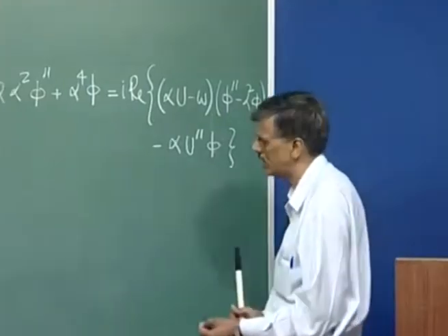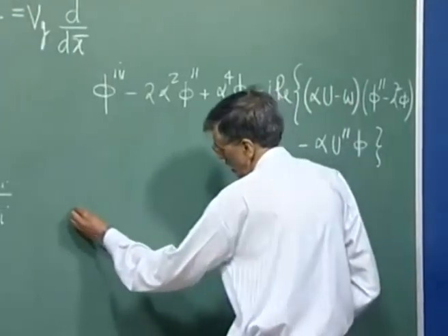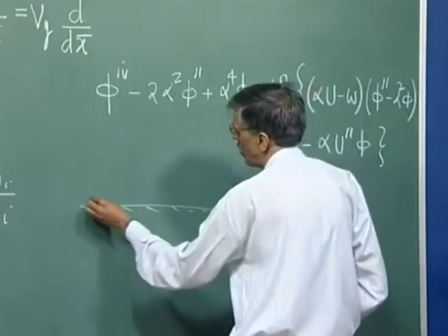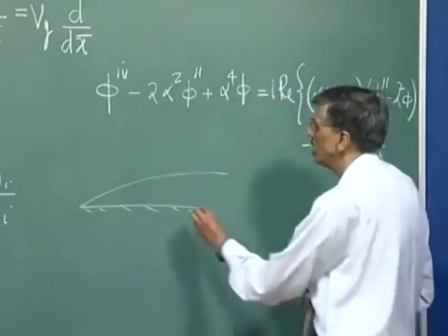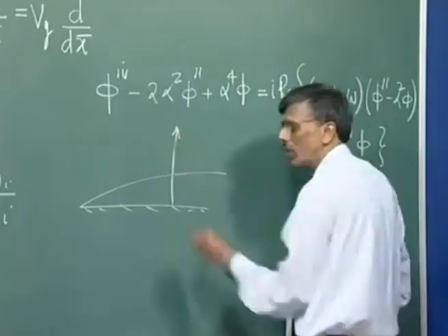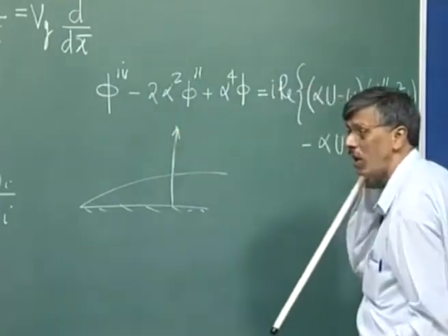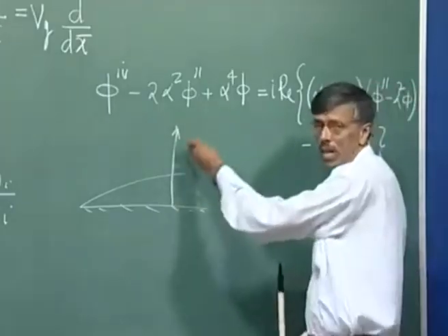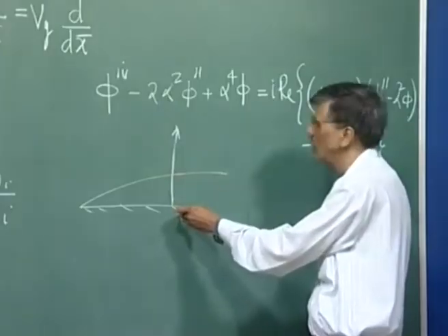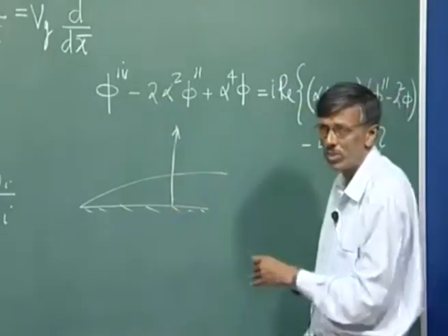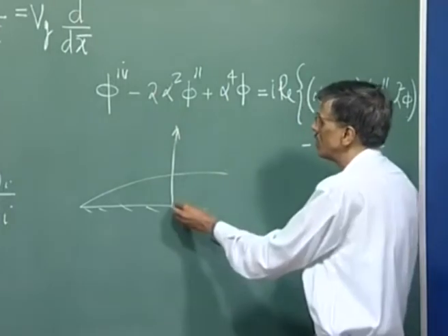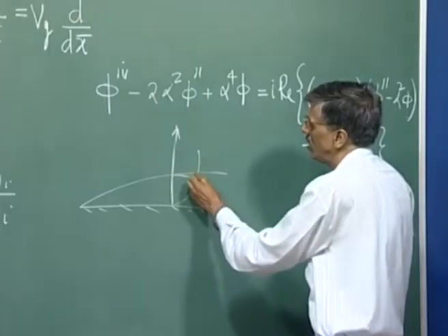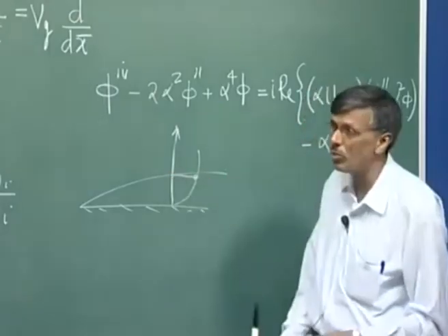However, if I am looking at, let us say, flow over a flat surface with a sharp leading edge, a boundary layer forming like this, and if I go along this, you understand that the solution of the equation does the analysis at a particular station x and solves this equation as a function of y. Here you have this u of y. Once you come to the edge of the shear layer, you have reached u equal to 1.